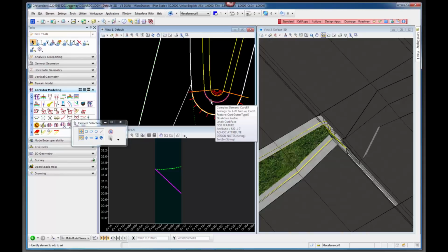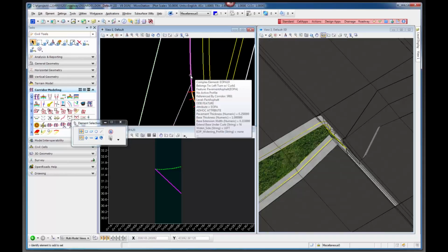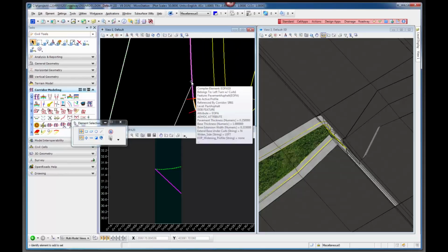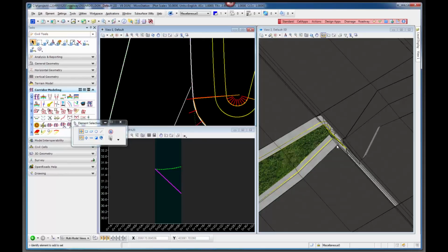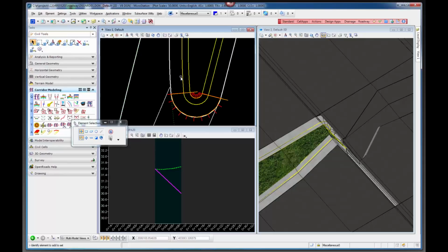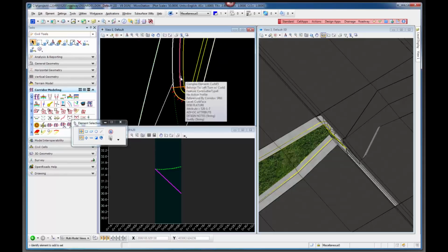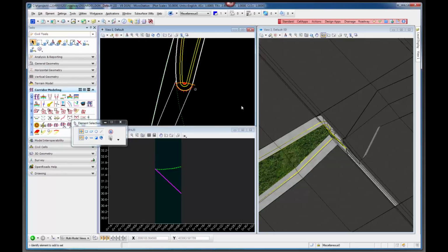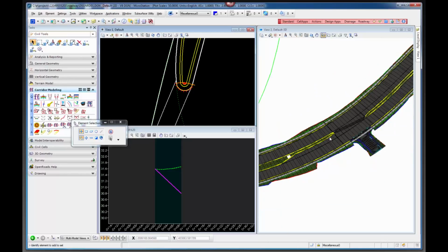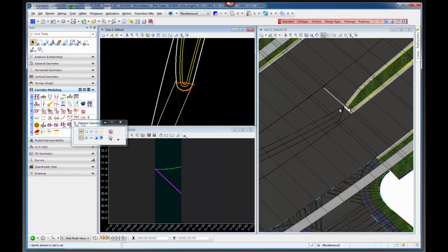The other thing is you want to make sure that you don't use any of the nose elements as corridor references, because you don't want the normal template to use these lines. Like now this one is using the edge of pavement line to draw it up to here. And then the same thing with the curbs that trigger on the curb median components. Now I've spent some time detailing out another intersection, so I'm going to open that up.